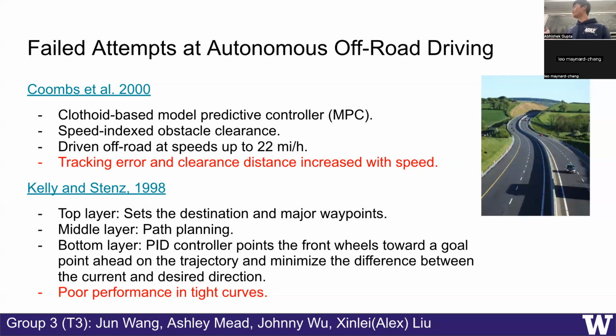However, this method doesn't really work because of its poor performance in tight curves. When the curves are very tight, not like the curves shown in the picture, but almost 90-degree curves, the error will be huge because they don't have time to react to the change in orientation.